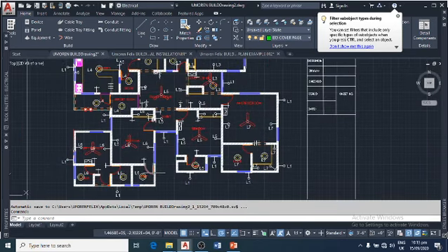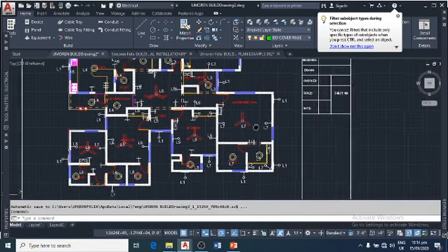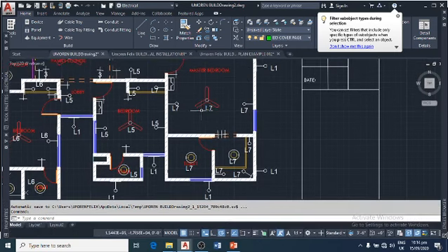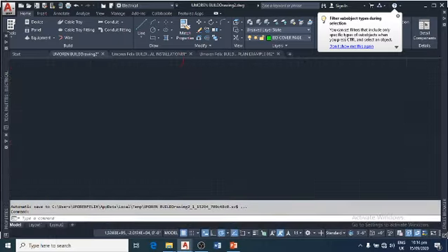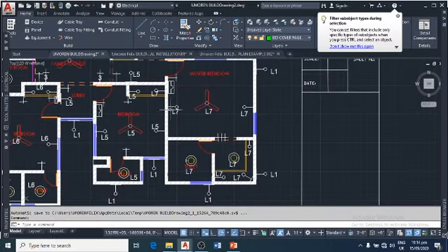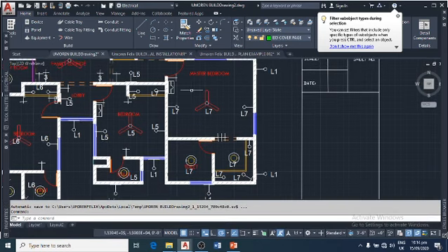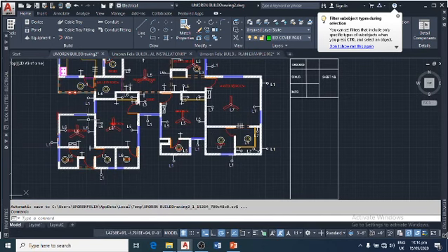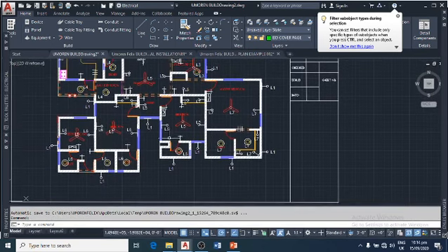Moreover, during maintenance, it will help us to maintain a particular part of the building without affecting other parts of the building. For example, we have our master bedroom, which is comprised of the L7 subcircuit. If we have a fault in the master bedroom, we go to the circuit breaker and pull out only those connected to L7. Hence, L1 to L6, all the components will be working fine. They will maintain just L7. After that, you can put back on those connected to L7. That is the significance of creating subcircuits.